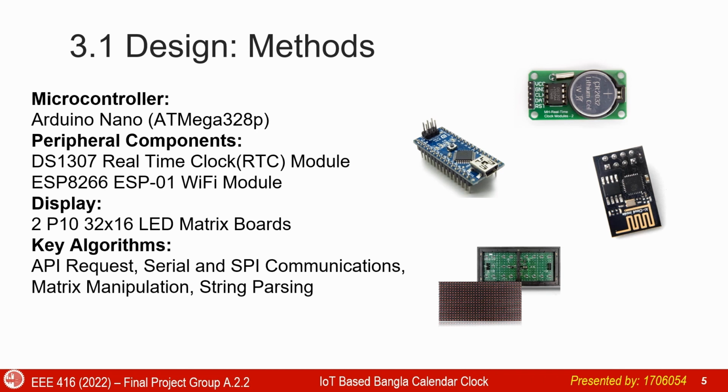We merged two 32 by 16 LED matrix to display our data. In our Arduino code, we implemented serial and SPI communication. We have done string parsing and manipulated matrix in order to show our final output in LED matrix board.